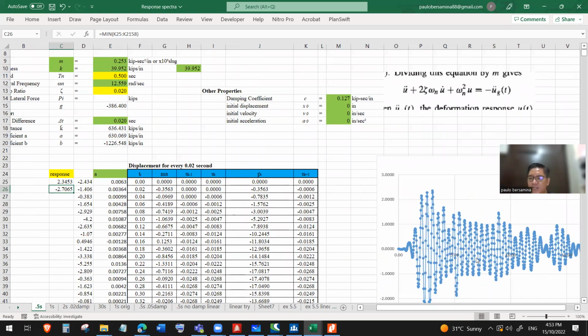That's why one of the retrofitting approaches for old buildings is inserting damping material, dampers, because they reduce the deformation during an earthquake. In Taiwan they use what they call a tuned mass damper, because mathematically it reduces the deformation of your structure.